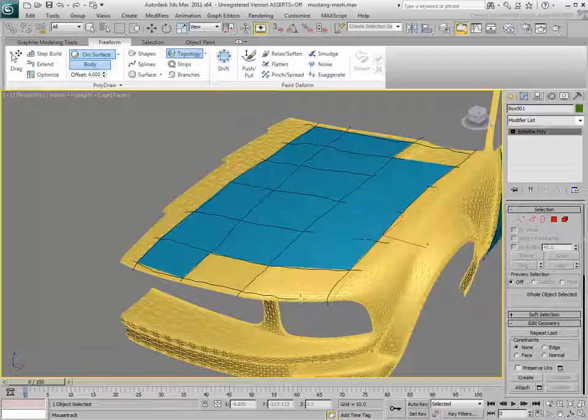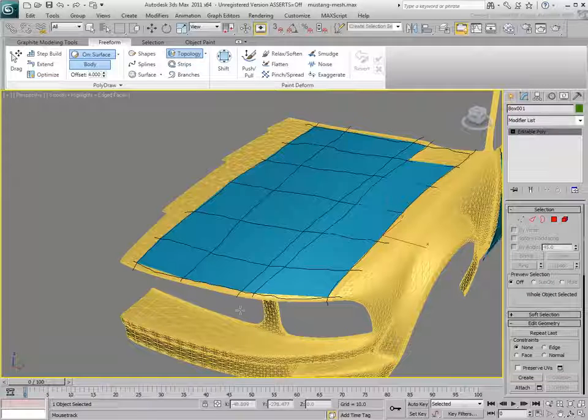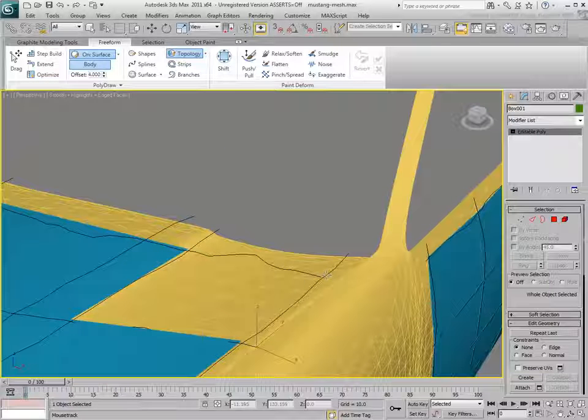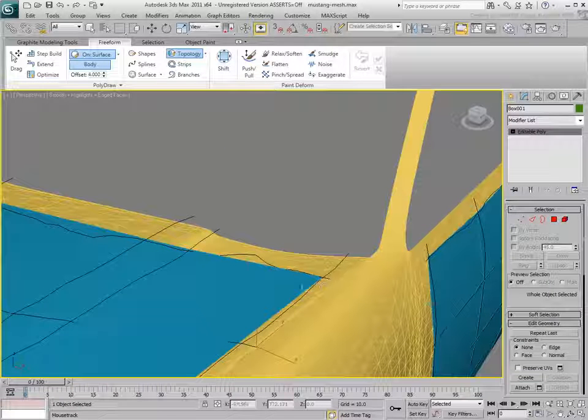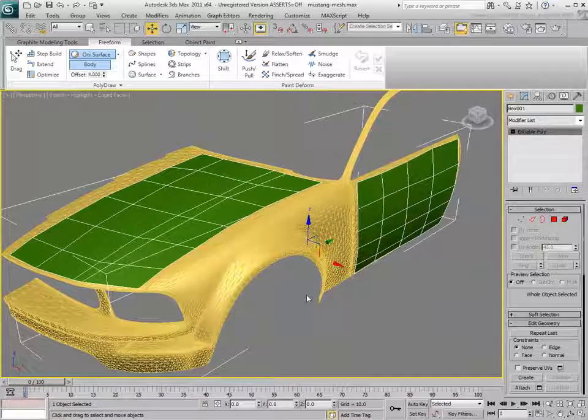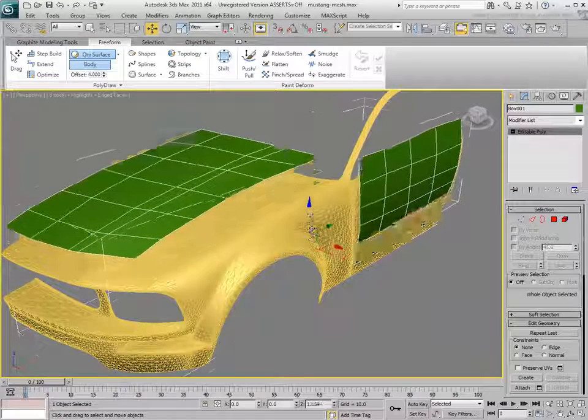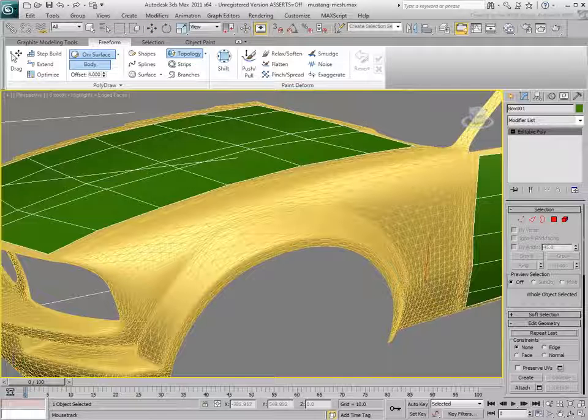If you inadvertently remove a grid line using the Control key, you can always draw it back, even if it is in the inner part of the surface. To fix gaps, zoom in and extend any short grid lines with the help of the Shift key. Ultimately, a right-click ends the process, and you are left with the resulting poly object that you can edit using regular poly editing tools, now that the basic work is done.